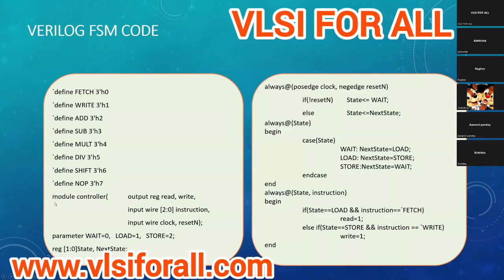Now we have declared a module controller with output variables read and write, and inputs instruction, clock, and reset. Then we have declared 3 parameters: wait, load, and store. Here we used parameter, but we could have used an enum also. Imagine this as an enum of wait, load, and store: wait will automatically be 0, load will be 1, and store will be 2.